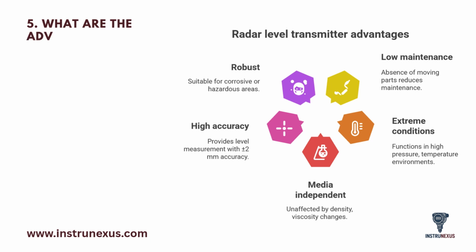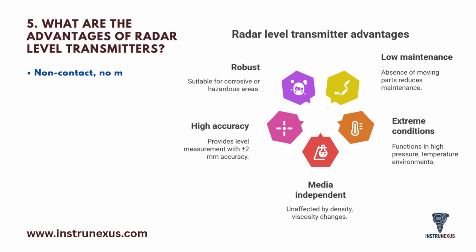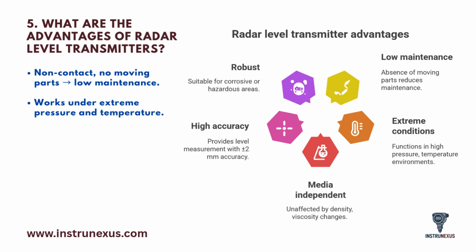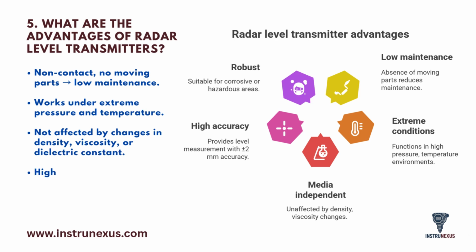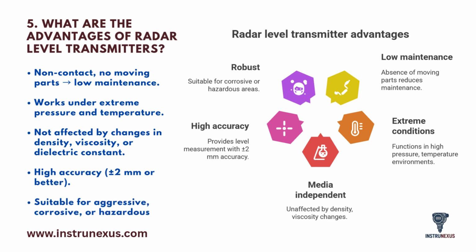What are the advantages of radar level transmitters? Non-contact, no moving parts, low maintenance. Works under extreme pressure and temperature. Not affected by changes in density, viscosity, or dielectric constant. High accuracy, plus or minus 2 mm or better. Suitable for aggressive, corrosive, or hazardous environments.